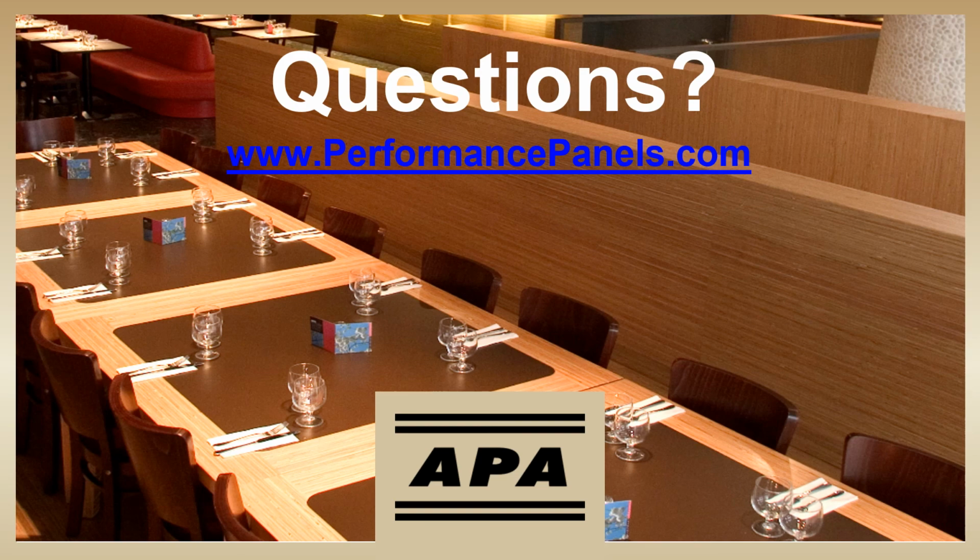Our next question is, you mentioned that a 4-ply panel has 3 layers. Can you explain what that means? That can definitely be a little bit confusing. So if you think about the direction of the grain of the plies, they're going to be perpendicular as the panel is laid up. So, as an example, if the grain of the face ply is running in the long direction of the panel, which it almost always is, the next ply's grain is going to be oriented perpendicular to the direction of the face ply. And this same process is followed from the back of the panel as well.